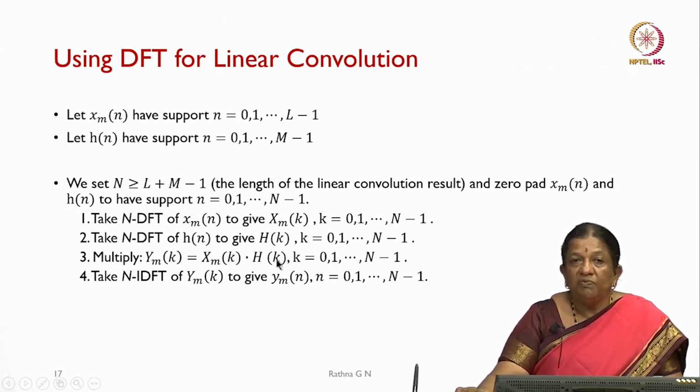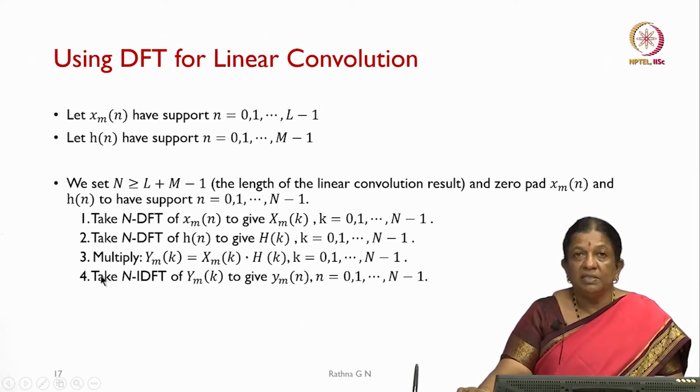Once we have the multiplication result, we take the N-point IDFT of Y_m[k] to give our y_m[n].